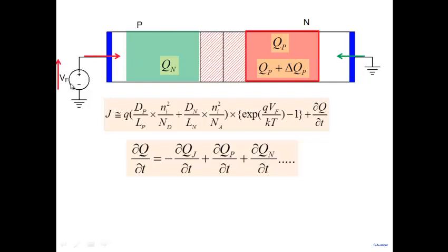If you don't change voltage, the charge is not changing, and I don't have this current here, del Q by del T. So in addition to junction charge, I have del QP by del T and del QN by del T. These are two additional charges in forward bias. QP and QN is what we call diffusion charge. They have come in because of an injection process, and after injection we know there is diffusion and recombination. So we call these excess holes here and excess electrons here.